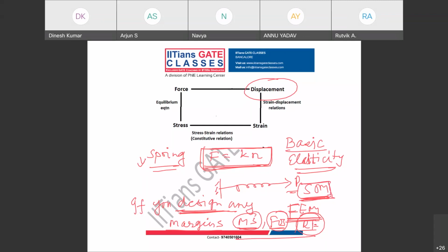Okay, so strength of material is a classical approach to do analysis. What does classical approach mean? If you can idealize your complicated structure as a simple axially loaded structure like a bar or rod, or as a shaft under torsional loading, or as a beam, which will have transverse load, then we can use the strength of material approach, because their exact solutions are there.